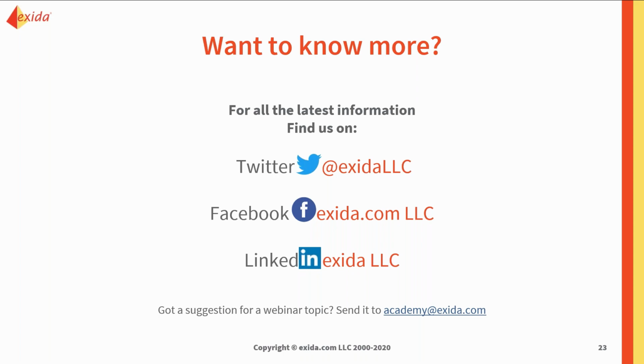I know for every exida certification, we have not only the safe failure rates on the reports and on the certificates. If you do have a product that's missing the failure rates, ask to see if it has a calibrated FMEDA report. Those should always have that. If not, you can always have an FMEDA done for your product to get that safe failure rate or a certificate. But hopefully, all of your certificates have that on them. I know if you use any of exida's, you'll definitely have that safe failure rate.